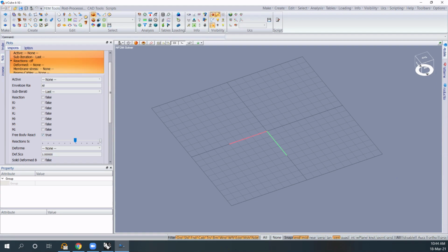Then what happens? Once I have a shape, we want to go to the next step. The next step is I want to start running a structural analysis. I want to apply the wind loads, the snow loads. I want to connect my membrane to the steel frame. So the initial pre-stress has to be a feasible pre-stress, a real-world pre-stress. So I have to look at the initial pre-stress, and if it is too high or too low, I have to scale it to be in the range of feasible pre-stresses. Just to give you an idea, a feasible pre-stress for a small or medium structure goes from 0.7 to 2 kilonewtons per meter. Okay.